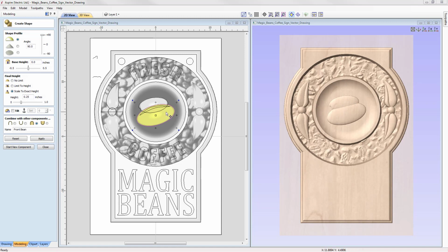So to do that, we could look at applying a tilt. Now, a tilt is basically like applying an angled base height. So if I check the tilt option here, we can use the set anchor tool, and then over in the 2D view we can apply our anchor point. So we're going to start by applying our anchor point at the bottom here. So you always want to start it where you least want to apply a height. Okay, so that's this bottom area here.